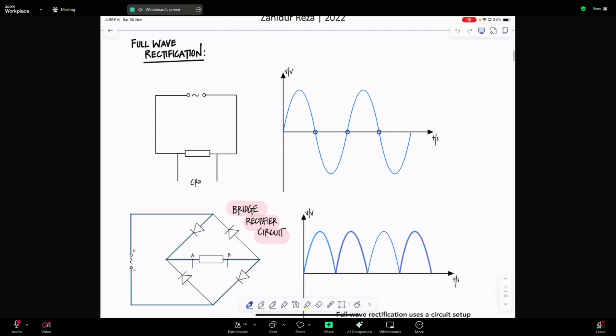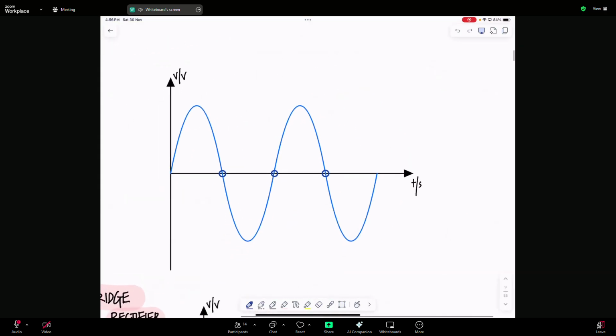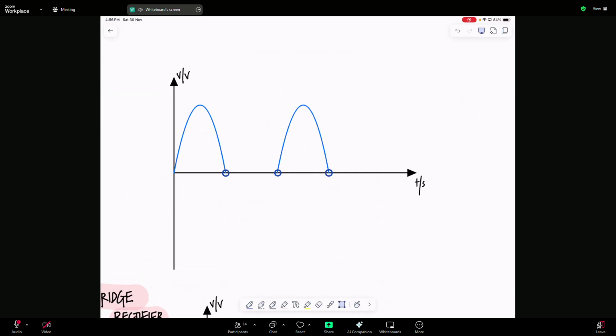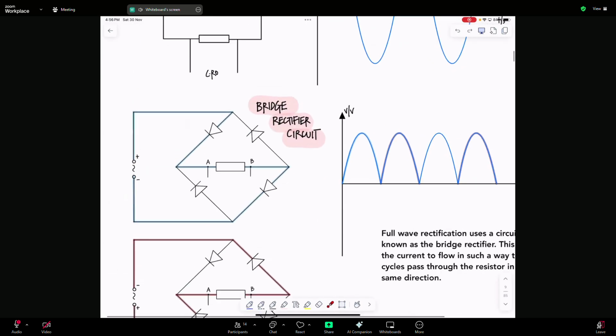So the first step in that is to place a what here? Diode. And once you place a diode here, can you tell me what would the output look like? Yeah, that, right? So that's fine. I mean, it did do its job, but you just wasted half the energy. Right? Just half the energy has disappeared. You're still paying for it, but not using it, right? So that's when they decided, is there a way we could do this? Like bring it back to the top. So they came up with this circuit. It's called a bridge rectifier.